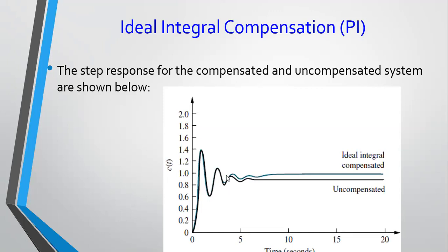Now, if you look at the transient part, you find your overshoot is the same as expected because you're operating along the same damping ratio line, and you find your peak time and your settling time are more or less the same, with slight change because the pole is not exactly at the same point, and the gain also has changed a little bit, but it's more or less the same, so that should not be a point of concern. So by simulating the system now, you're validating your result, you're validating, yes, the second order approximation is working fine.